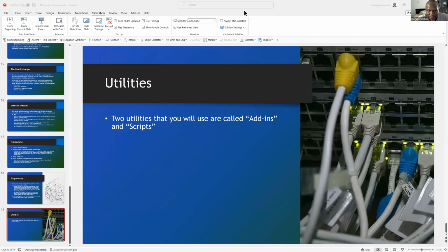Now, how does the API do the same thing? Almost step by step. First of all, there is an object that you can set a value to, and the value you give it becomes the name of the sketch plane that you are choosing. Once you choose that sketch plane, you then choose a circle object, and that circle object will be placed on that plane. It is now for you to set the value for the center where it will be located and for where the radius should be. You can give all that information into your Python, and once you finish that, a circle has been created on a sketch plane. Finish.